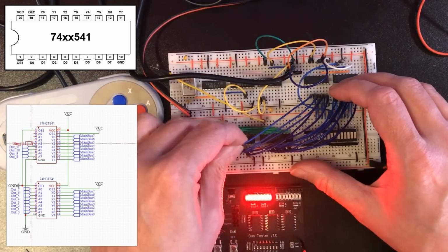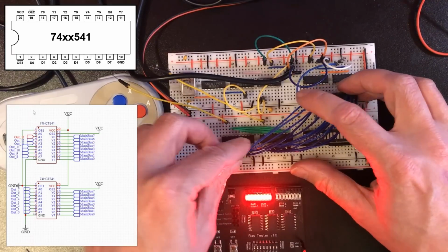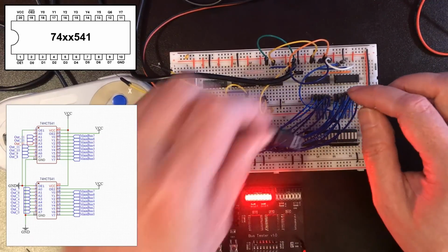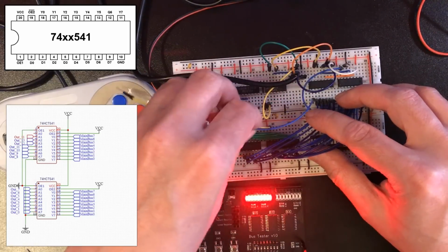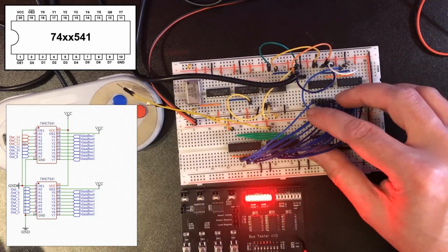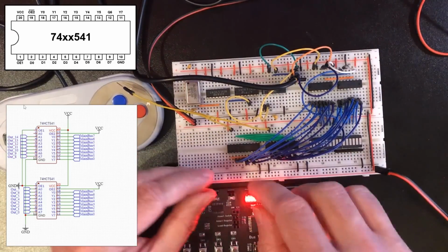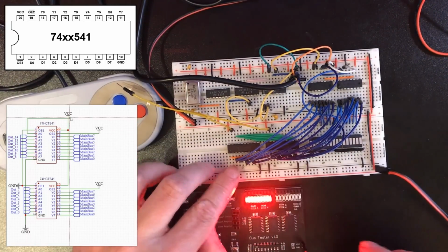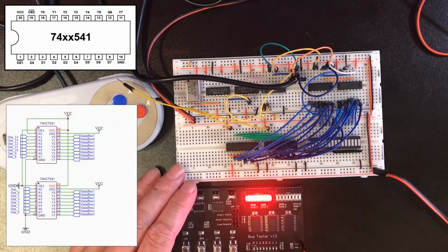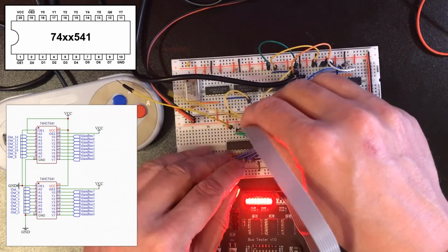I'm going to take the next 3 bits from the next 3 bits in the shift register. We're not expecting those ever to be 0, but I don't think it's going to be particularly difficult to bring those bundles of wire across alongside the others. And then just the most significant bit we're going to pull high, and that's going to be our identifier so we know which is which. So let's plug the bus in.